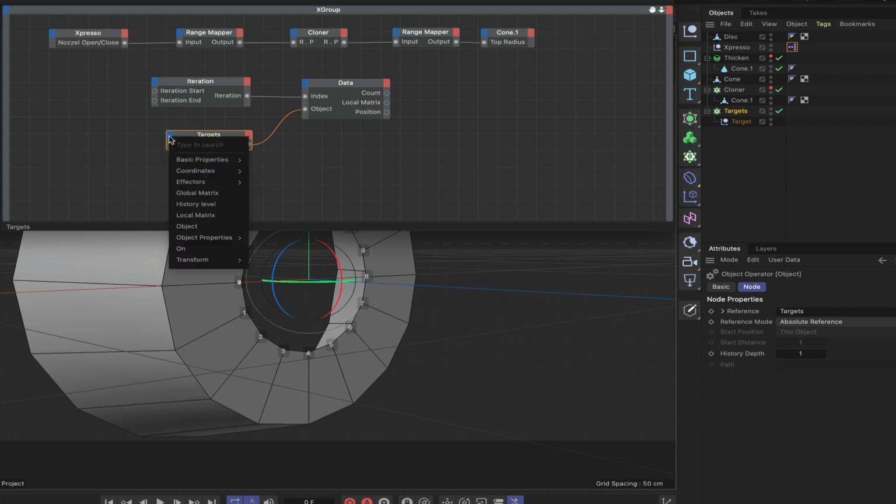We can then also add a radius port as well. So we'll come down to object properties, and if we can find it, we'll reach for radius. Oh, we got plane there. I want radius. Delete that one. Radius. So object properties, radius. There we go. So we've got our two input ports set up and ready to go.